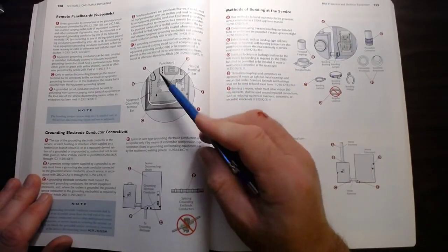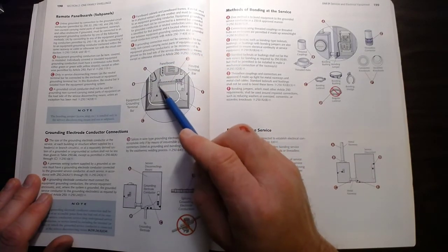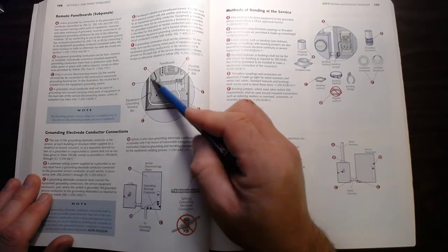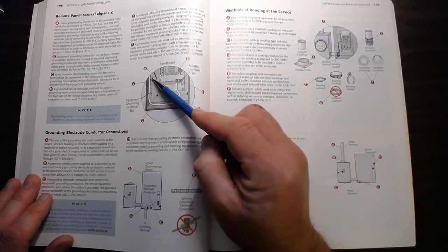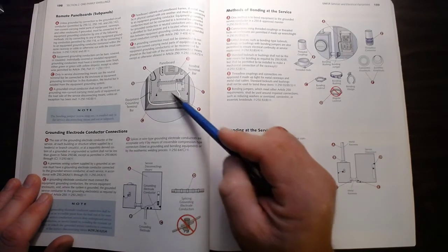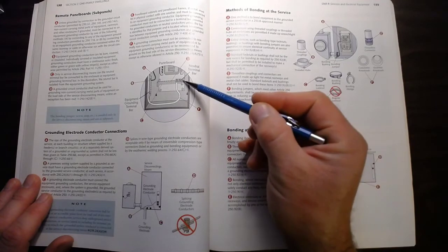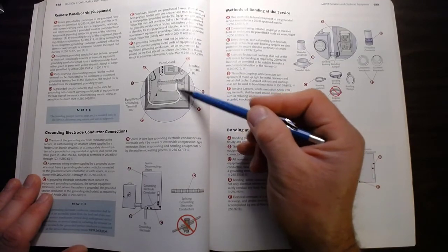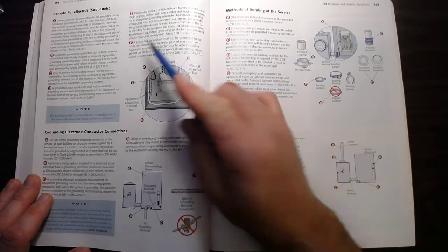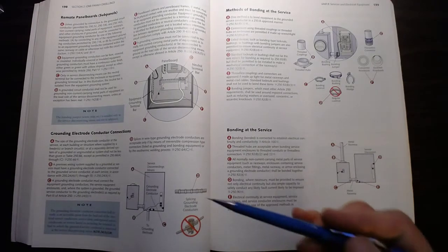Here's a picture of that. Remote panel boards or sub panels. We see that that is removed and the neutral now is insulated off of the metal backboard, and the grounding bus bar is installed now. Grounding bus bar is attached right to the back of the panel, and the insulated bus is raised off of plastic stanchions and keeps the neutral isolated. So this is very important. Again, all of these code sections are in here that you will need to look at.